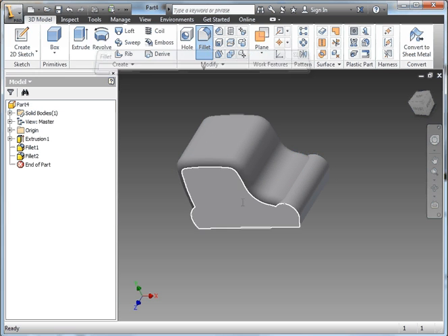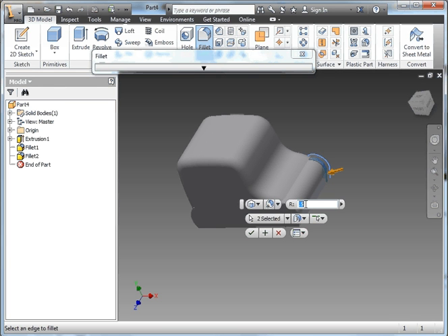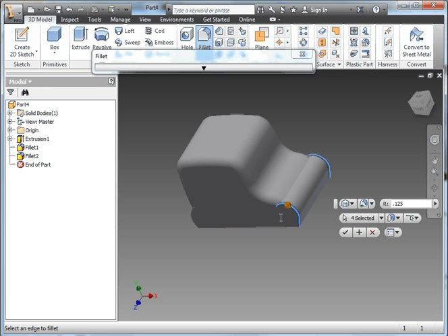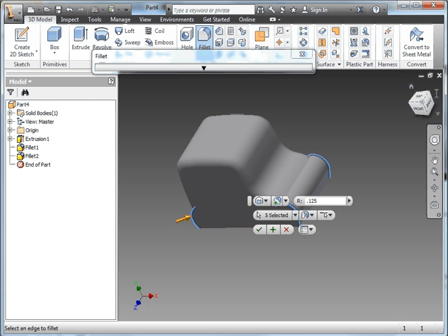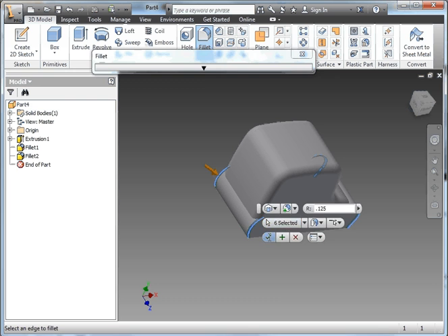And we'll do these quite small just to add some subtle little fillets to the car. We'll get those ones at the back too. I can rotate around, pick that other one, and check. So there we go. I've got some nice fillets wrapping around my car. It's not the nicest of cars, but again, it's fast for the tutorial.